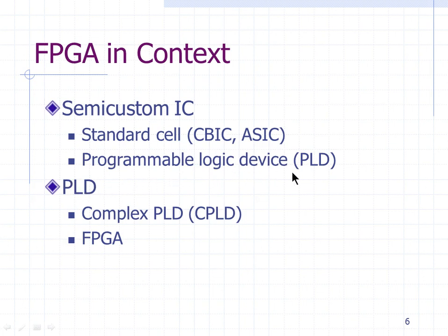PLD stands for programmable logic devices. So there is CPLD and FPGA. CPLD is a much smaller version of the FPGA. The overall number of pins is less. The capacity of the CPLD is less compared to an FPGA, and some other things. So CPLD is a much smaller version of an FPGA, and FPGA is a much bigger version. But they are both programmable, and both can be programmed or designed using Verilog as a design language.